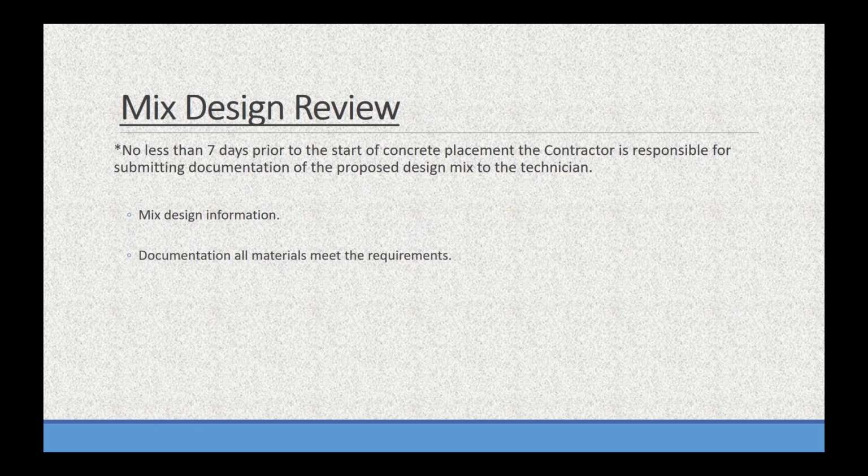And then documentation for all the materials that are incorporated into the concrete. So that's where some of those product data sheets for the admixtures or those certifications for the cement or fly ash, things like that, come into play. So you really need both. You need to check the actual mix design and the materials that are incorporated in it.